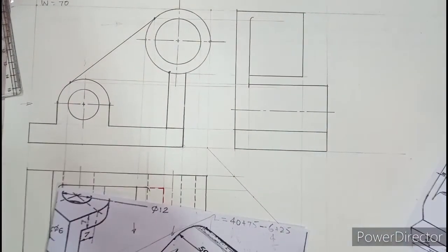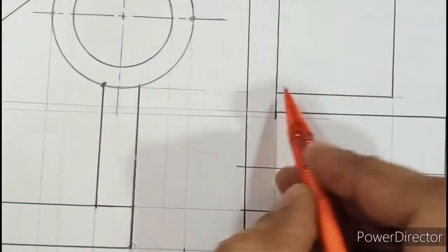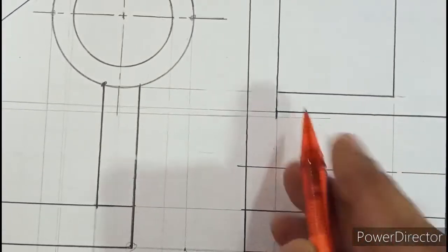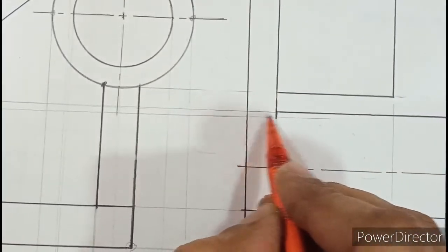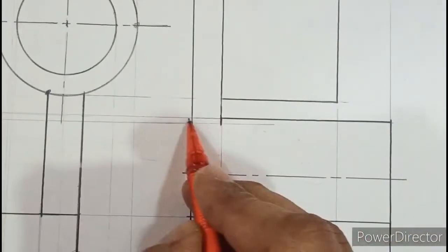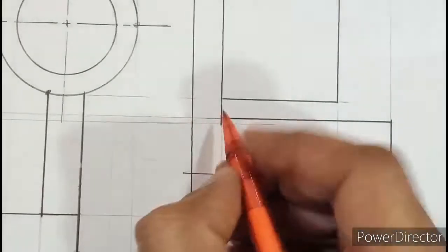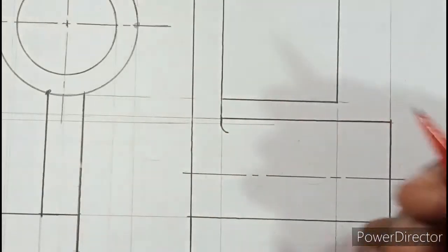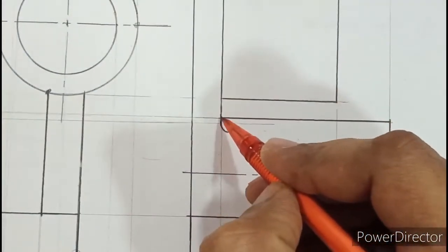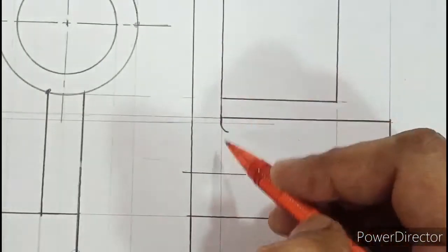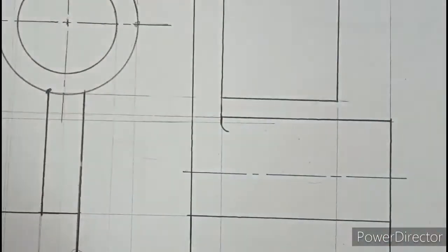Same way here, let me enlarge. So you can see that the merging point is slightly below this horizontal line. So a small surface of 10 mm merges with a large surface of 70, isn't it? So this surface is 70 mm, this is only 10. So the arc should be towards 70. So beyond this you should draw a freehand arc. It should be a continuous and smooth arc. There should not be any sudden jerks. So this is the symbol of merging, which you compulsorily show in both the views.